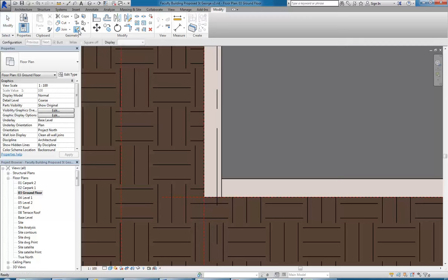So when you click on wall joins, then you can go to any two connected or more than two connected walls, and when you hover over that join, you'll see this square come up. If you click there, then it's going to select that wall join, and then you can see you've got butt and miter as the two different automatic joining options. Sometimes you'll get square off as well. So you can switch between those two options. Butt is what you can see there, where the walls are joining at right angles. If you change to miter, you'll get a 45-degree join, which can be really useful for certain kinds of walls, but not this type. So here, butt is the option I want, and I'm going to go to next,